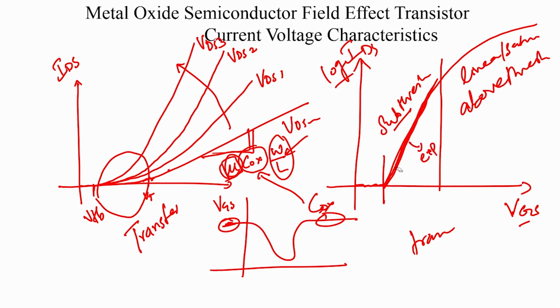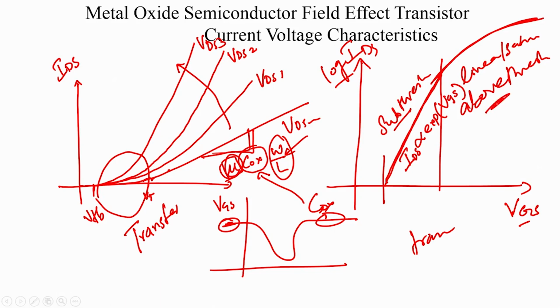But having said that, when we talk about non-crystalline semiconductors, we will see that there are some variations in the subthreshold slope itself because of the existence of states inside the band gap. But for now, what this lecture tells you is that this should be a straight line, because the current is exponentially dependent on the surface potential or the VGS, and then you have an entry into the above threshold region, and this knee of the curve sort of defines what your threshold voltage is.